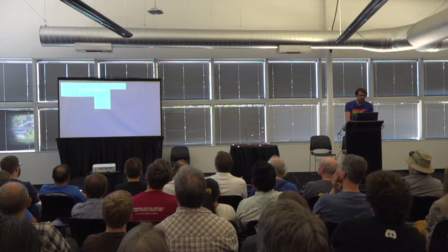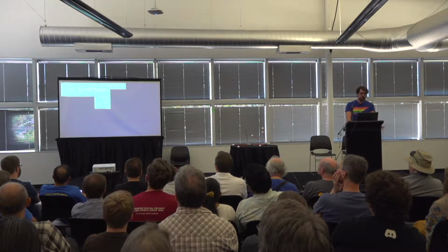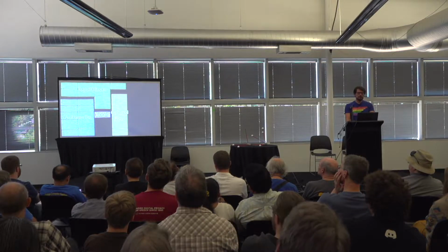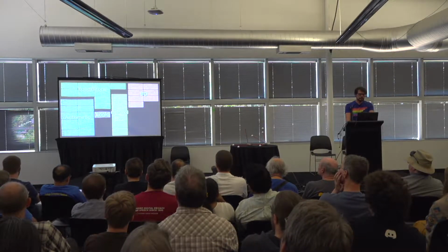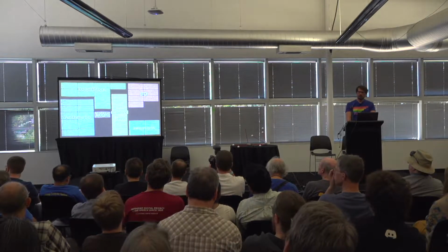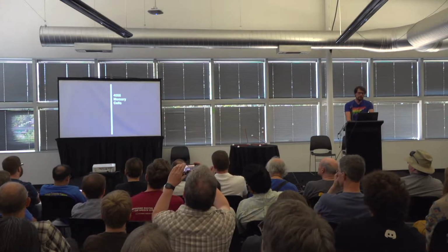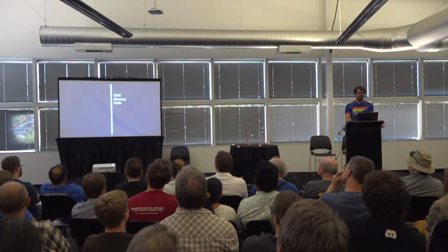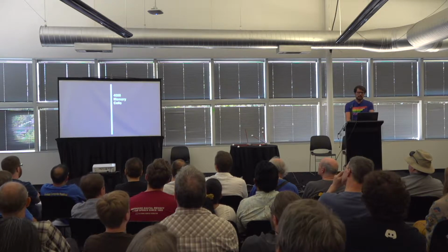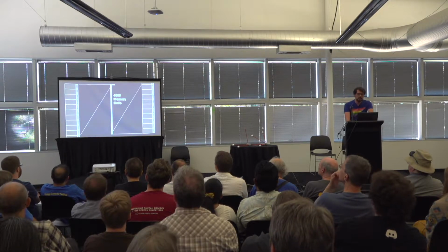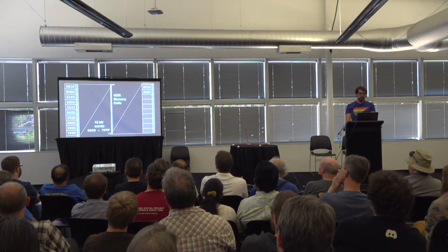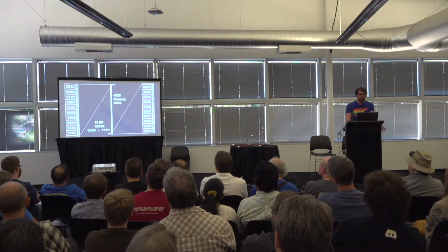These are the 36 instructions. Some load and store instructions, arithmetic and logic, control flow instructions, I/O instructions, and instructions for dealing with interrupts. The memory model is the cornerstone of the instruction set. Memory consists of 4,096 cells, numbered hexadecimal 000 through FFF. Each cell contains a 15-bit word, a number between 0 and 7FFF.